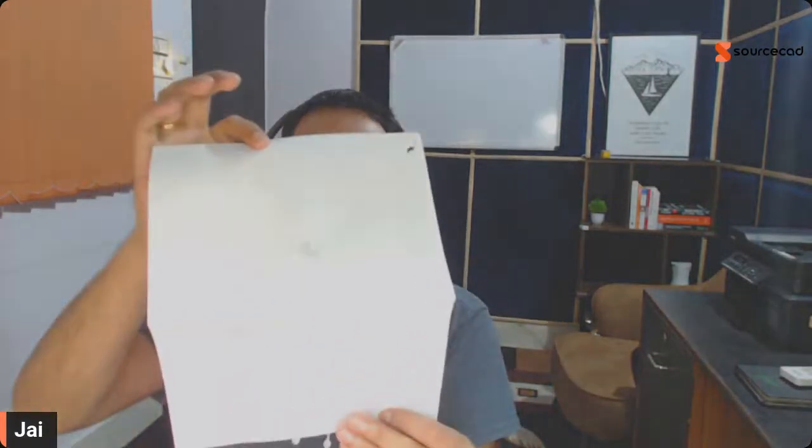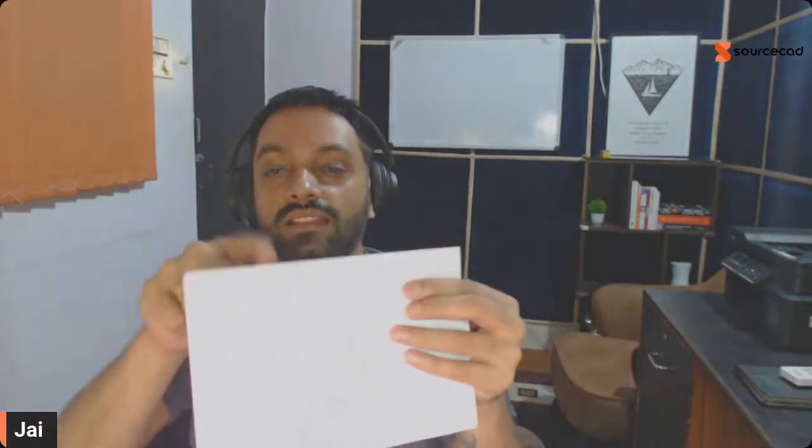But if not, then if you measure the length of this ISO paper and its width, then divide the two numbers. By the way, this is 297 mm, this is 210 mm. Divided, the number you are going to get is 1.414, which is the square root of 2. Now fold that paper in half from the longer side. Now divide the length by the width. You're going to get 1.414, again root 2.